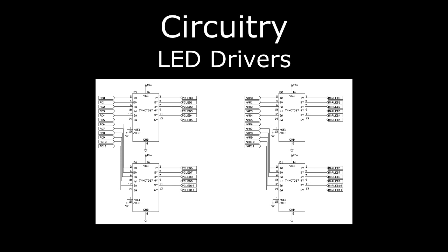The other thing, of course, is that speed is not a concern. These are a little slower than certainly F-series 74 TTL chips would be, but since it's a human interface, there's no reason to worry about a few tens of nanoseconds difference.